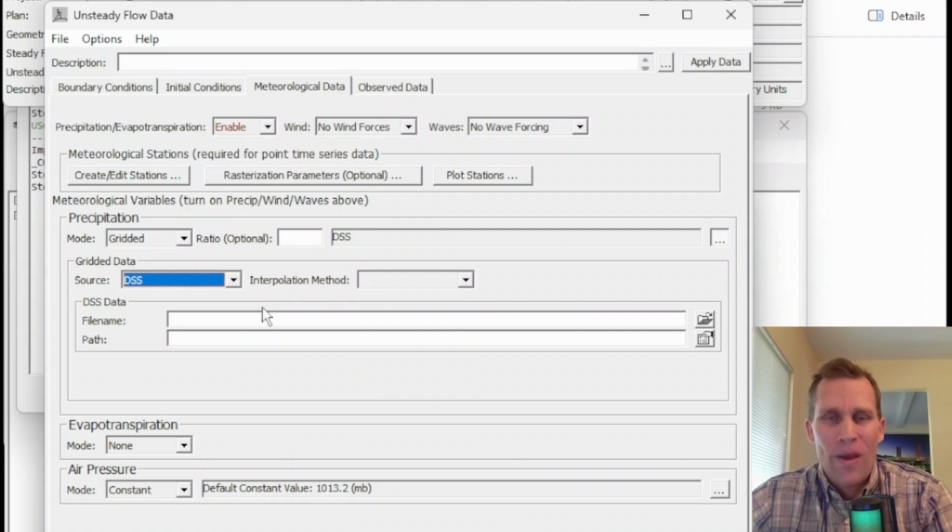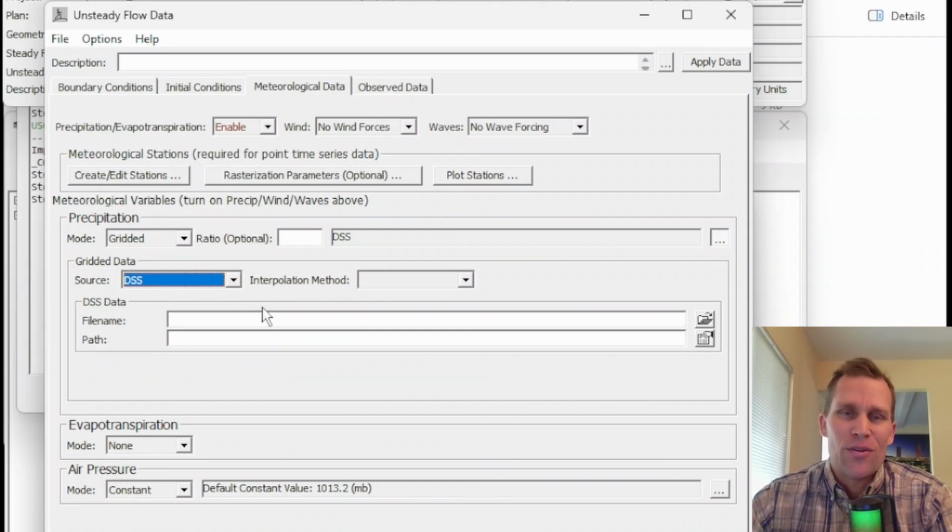So basically, we've got those PRISM files downloaded. But what we need to do is only import the PRISM files to our specific projection and also to our area of interest, which is that northern Colorado South Platte River region. And to do that, we need to create a shapefile to mask out all the other areas within the continental United States we don't need precipitation data for. So we're going to go ahead and create a shapefile to use as a mask for the importer tool, and we already have the projection file.